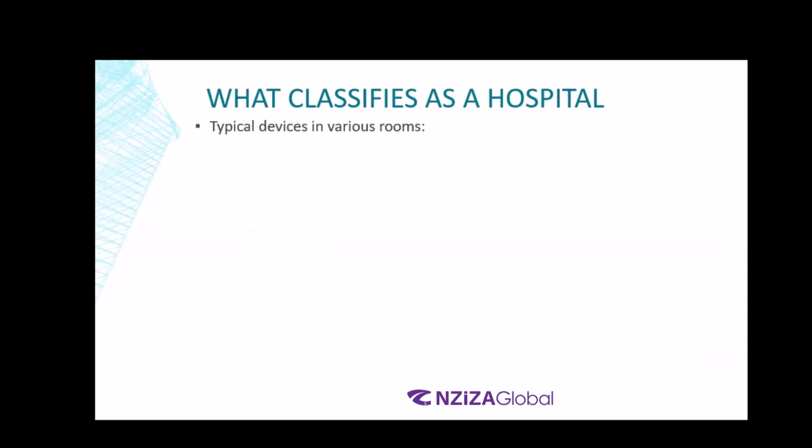So now let's talk about the offices. All right, you have doctor's offices. You will have 3 receptacles near the desk. It can be on utility power. This is not something that is a life safety issue. You can have 3 receptacles, 2 near his desk, 1 on top for the X-ray reading machine, which will have